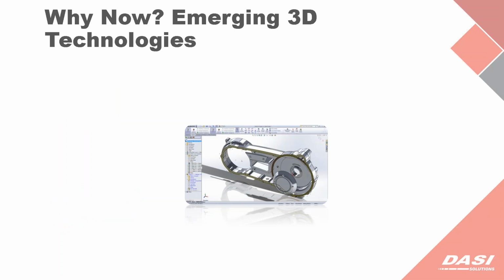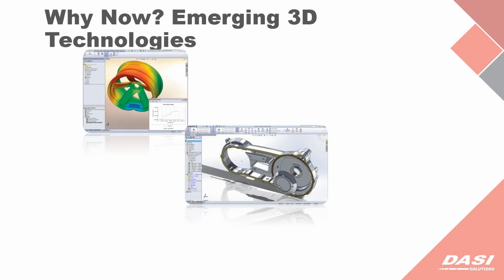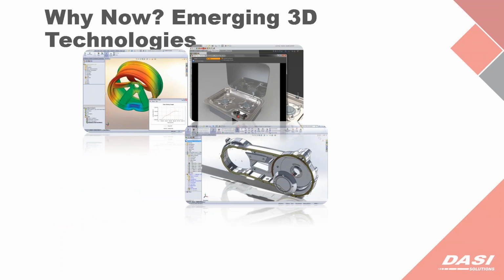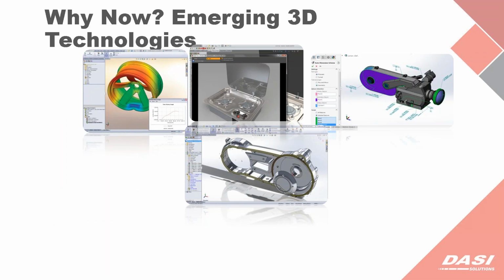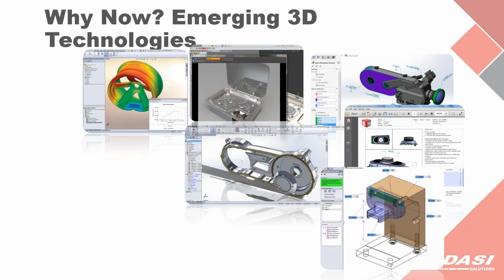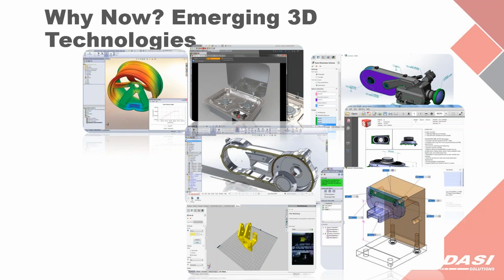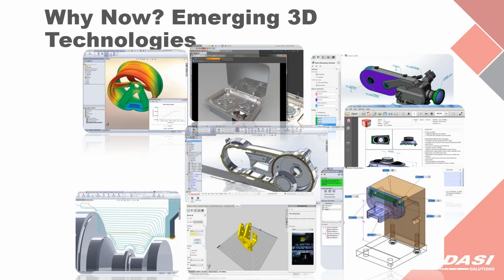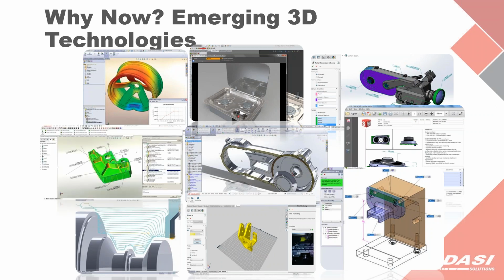And again, the idea behind this is that we're going to take the 3D CAD model, the thing that we use to generate things like simulation and photo renders, and we're going to start to create the model information inside of it, the tolerance values, the dimensions. We're going to put those in 3D PDFs that are easily readable by all users and pass that information along into other systems so we can do things like stack-up analysis, 3D printing, machining, and finally just inspection.